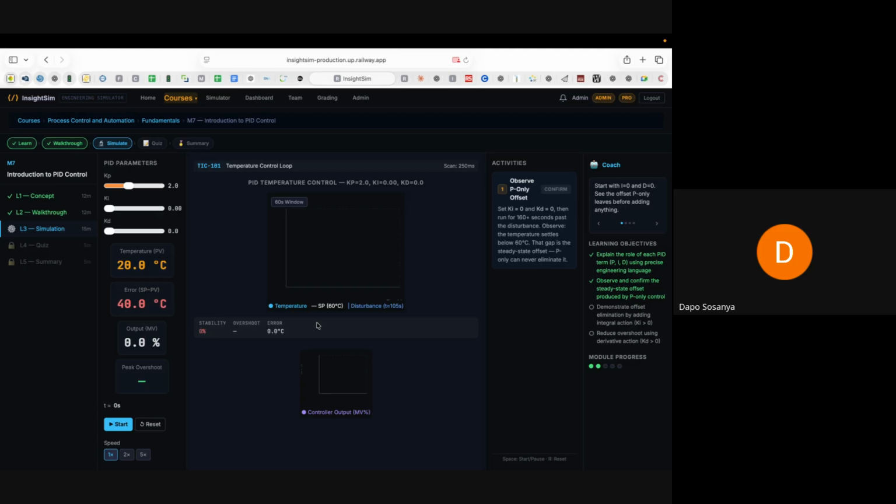The bonnet design determines whether it's going to be fail open or fail close. You can supply air from the top or from the bottom of the bonnet. The point at which you supply that air determines whether it's going to be fail open or fail close. But drop this question in the chat group and let's brainstorm on it. Let me quickly spend time on this simulator here.